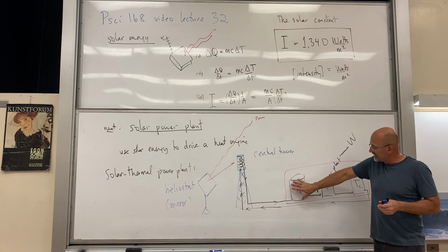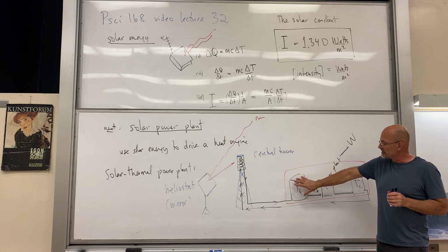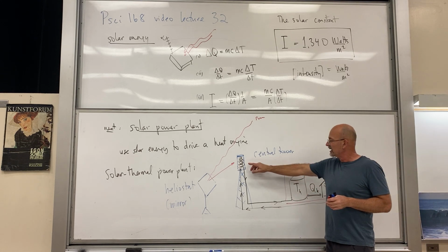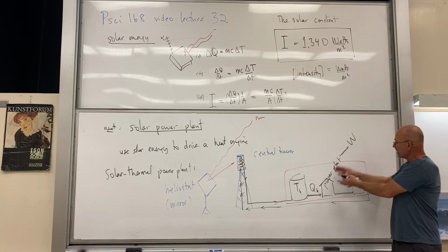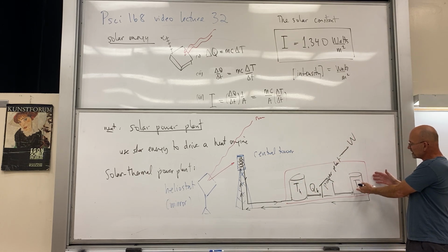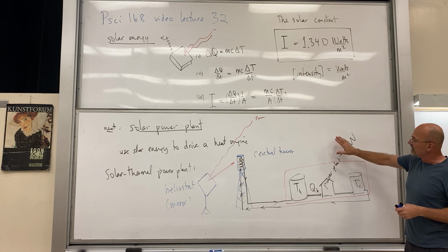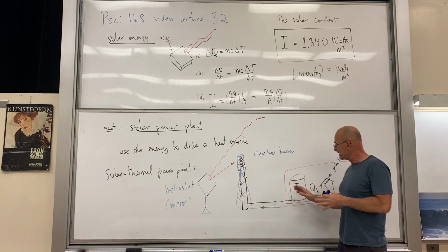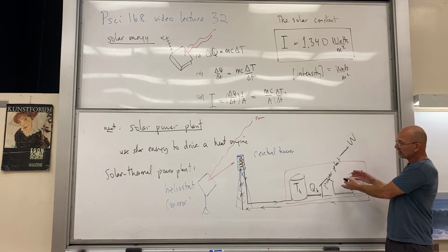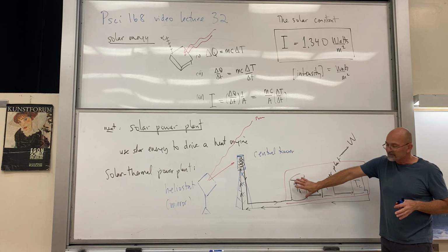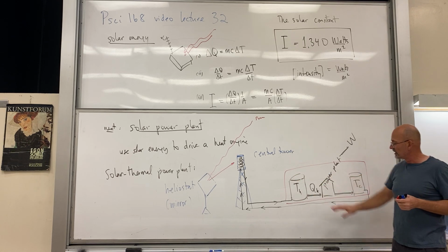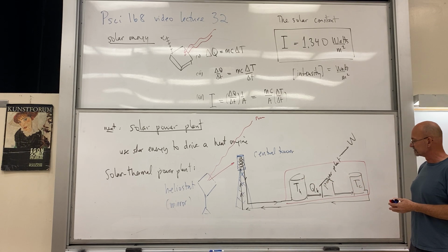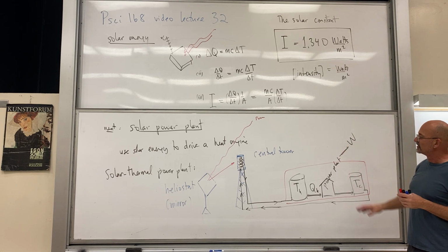What these are actually depends, but one solution is to use some salt that is molten salt, very, very hot, and the power plant delivers work, low temperature storage. This system can even function at night, okay? Because during the day, you're storing up all that heat, running your power plant at night. If you have enough here, or cloudy days and so forth, you have enough to continue running the system. Okay, so that's the basic scenario.